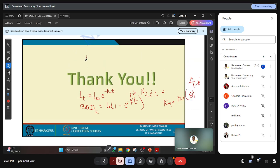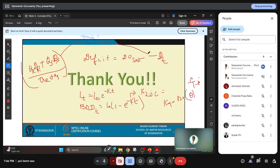And DO deficit is equal to DO saturation minus DO at any time t. How to find DO at any time t? If you are asked at the mixing point, then it is Q of the river into DO of the river, plus the sewage flow into DO of the sewage, divided by the total flow, Q_R plus Q_S. You got it? Then you can find the mixed DO that you can substitute here.